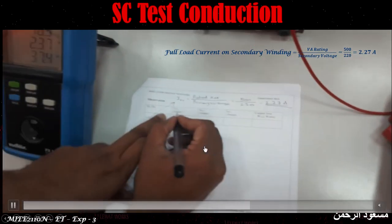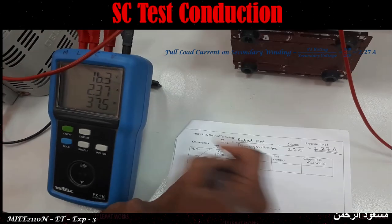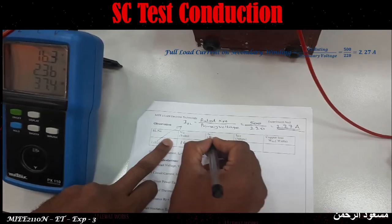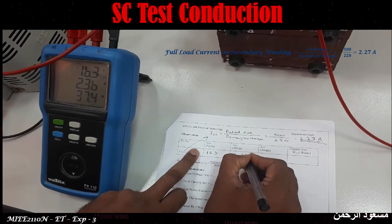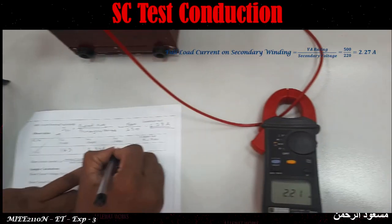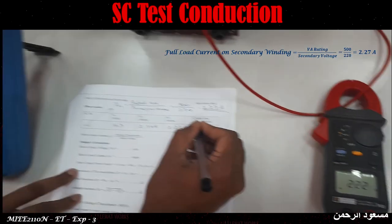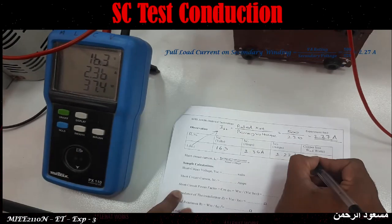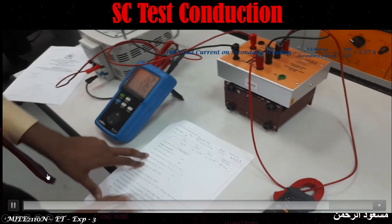After supplying 2.27 amps, note down the primary parameters: VSC is the first value, ISC1 is the second reading in the meter, the third reading is ISC2, about 2.27 amps, and the fourth, last important reading is WSC.